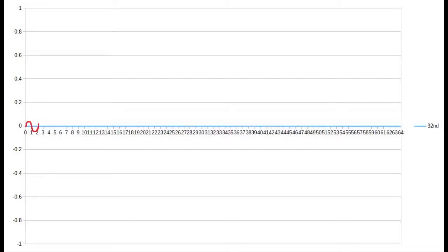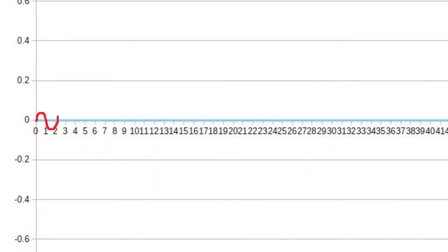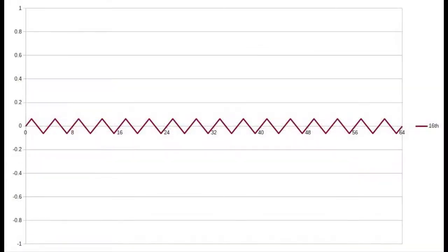Well, here it is, or one cycle of it hand drawn in. You can see that the value of the waveform is 0 at the sample points, so that's no good. Indeed, if we look back at the 16th harmonic, that triangle wave is what our interpolation algorithm is going to give us, not the sine wave we want. The result will be digital noise. We'll find out just how much this noise is in a minute.